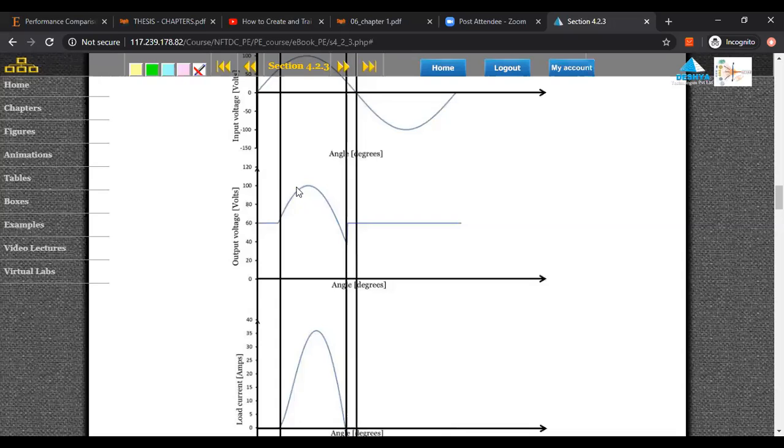Okay. So this is a behavior of the diode, we know very well. And this reverse behavior and jumping up is a behavior of your inductor. Just now I said, even though after this point it should not conduct as per the current, because of the energy stored in the inductor, it conducts in the reverse and comes back to 0. So I think that's very much clear.